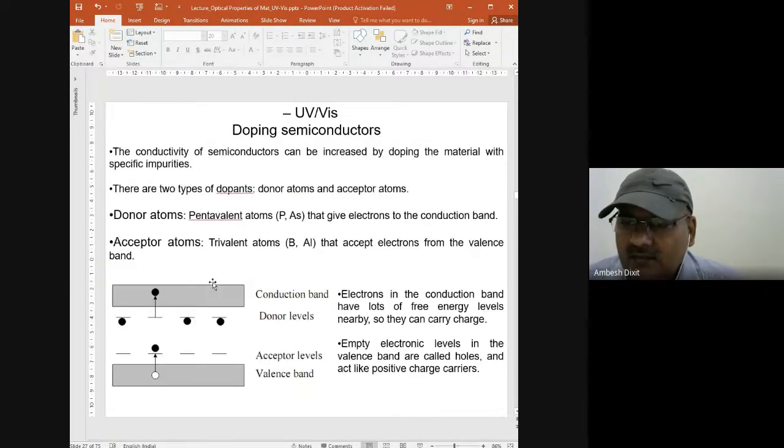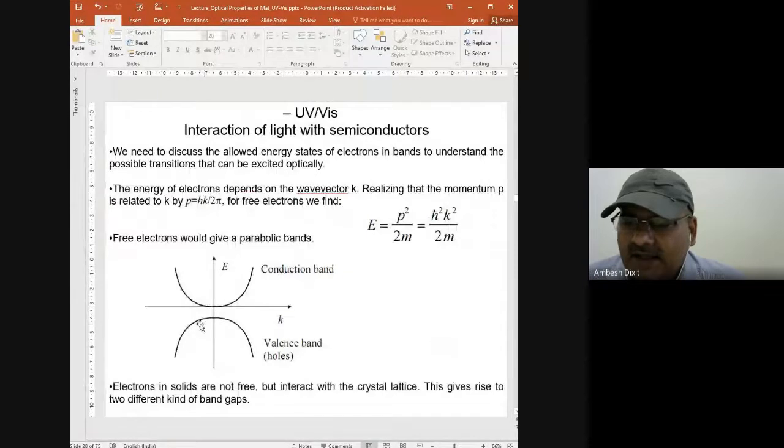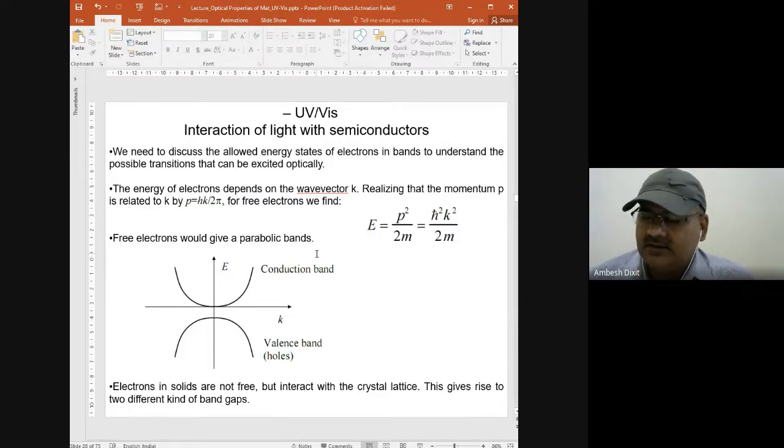And we can measure alpha from this simple experiment. We see the energy band diagram, and if it is a direct band gap, then it is a k equal to 0 process. There is no momentum transfer involved. Energy is directly taken from the valence band electron, shifting it to the conduction band. Right. In that case, the valence band maxima and conduction band minima are at the same point. So very simply we can see that no phonon is involved to satisfy the need of momentum conservation.